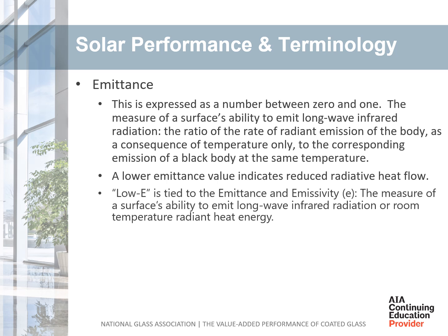Emittance refers to the amount of heat a surface can radiate. A so-called perfect black body can emit heat at a value of 1. A perfect non-radiant product would thus have a rating of 0. Low E glass is designed to have as low a value as possible. High-performance low E glass products have been designed to have an emissivity of less than 0.04.